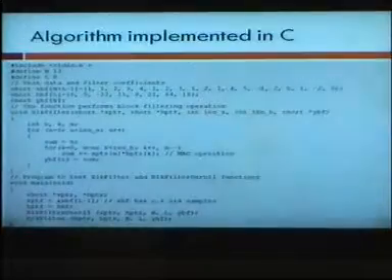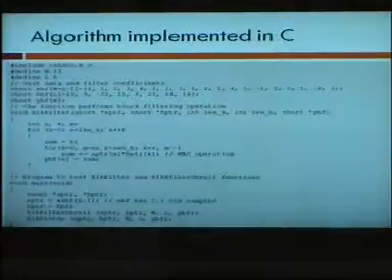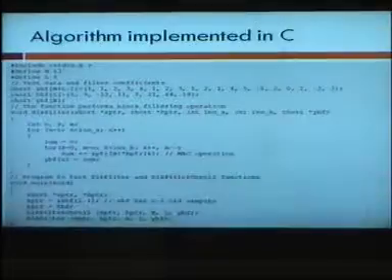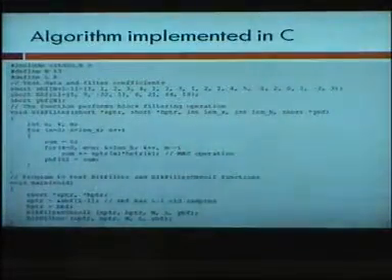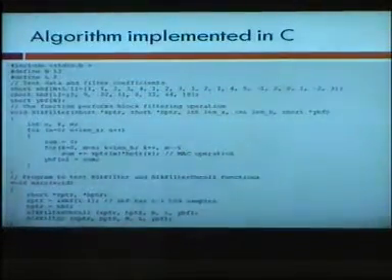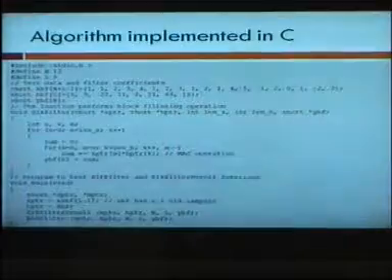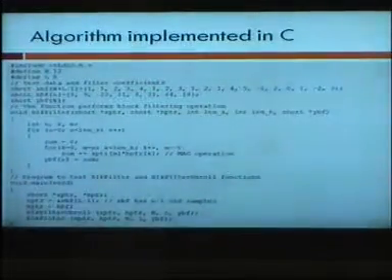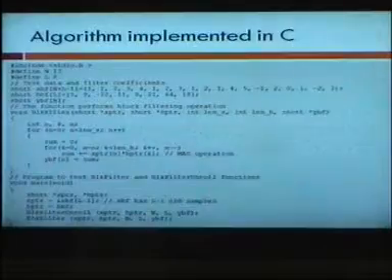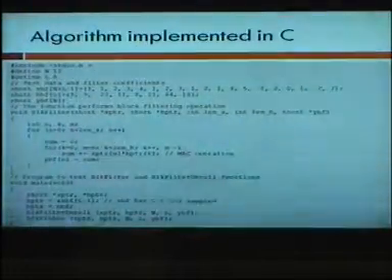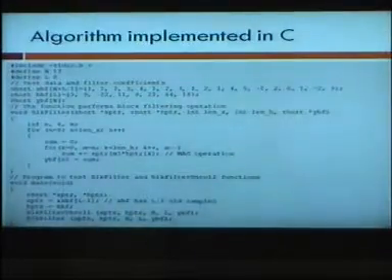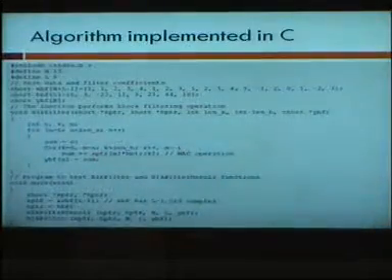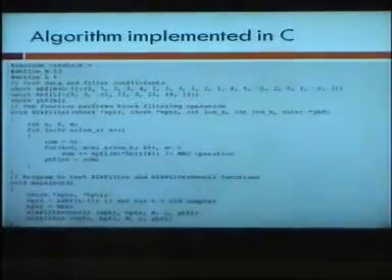Sometimes in signal processing applications, your requirements are such that you don't have these many extra cycles to waste. You just cannot call a function, and you don't want your processor to wait, maintaining the loop just to execute one instruction. So all this you are paying to execute one instruction. It's a huge overhead, perhaps 90% overhead, and you're doing only 10% actual work in this piece of software. And it is usually the case in signal processing.